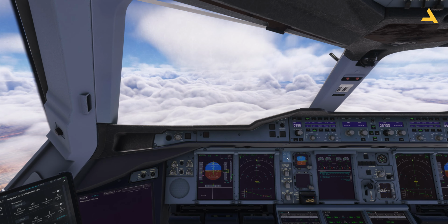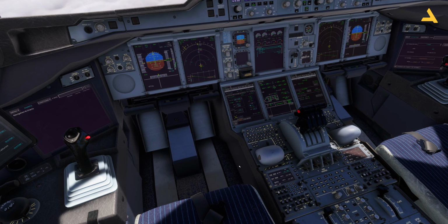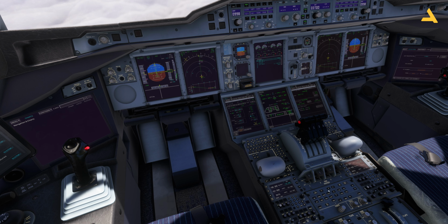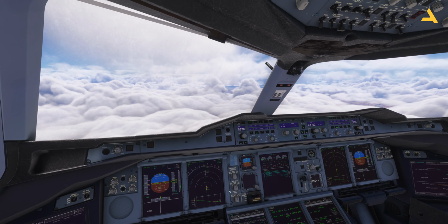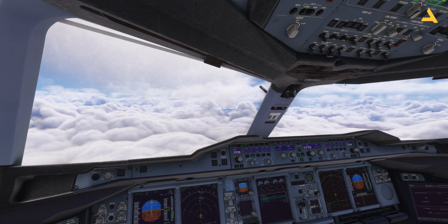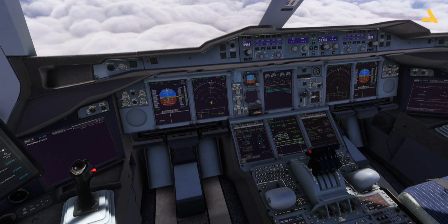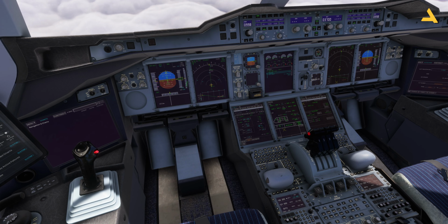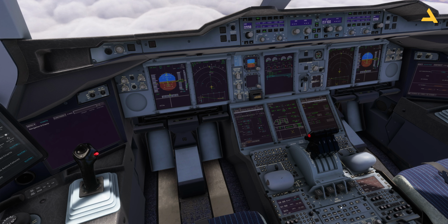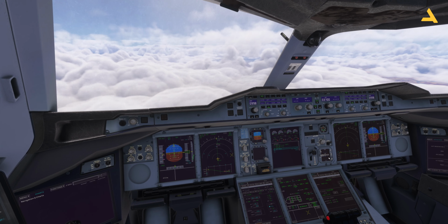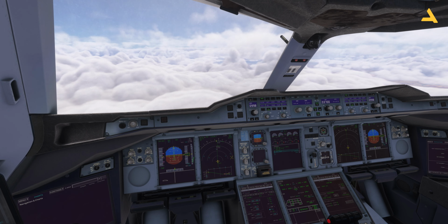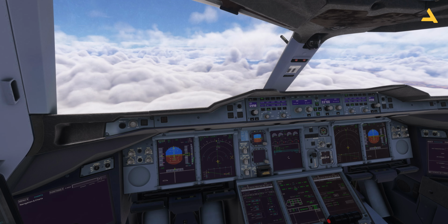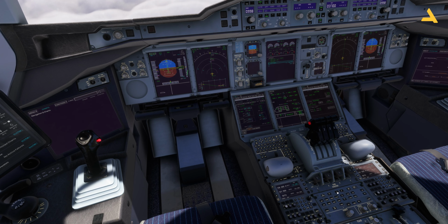It's cloudy in Islamabad. So baro reference, let's check it, and now this plane will be below 10,000 feet. So let's turn on the seatbelt signs. And minimums, I have set the minimums, and let's set the auto brakes. This is the control, and let's set it to max. And the checklist is complete.